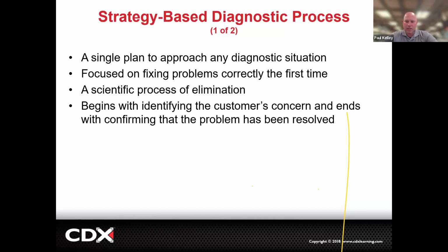that may be more like, let's say it blows warm air. Maybe there's no refrigerant. The refrigerant leaked out. It's got a leak. There's a lot of different potential causes. So the point is, we want to get on this path of coming up with a strategy to perform the diagnosis, to get a good diagnosis so we can sell the correct repair.